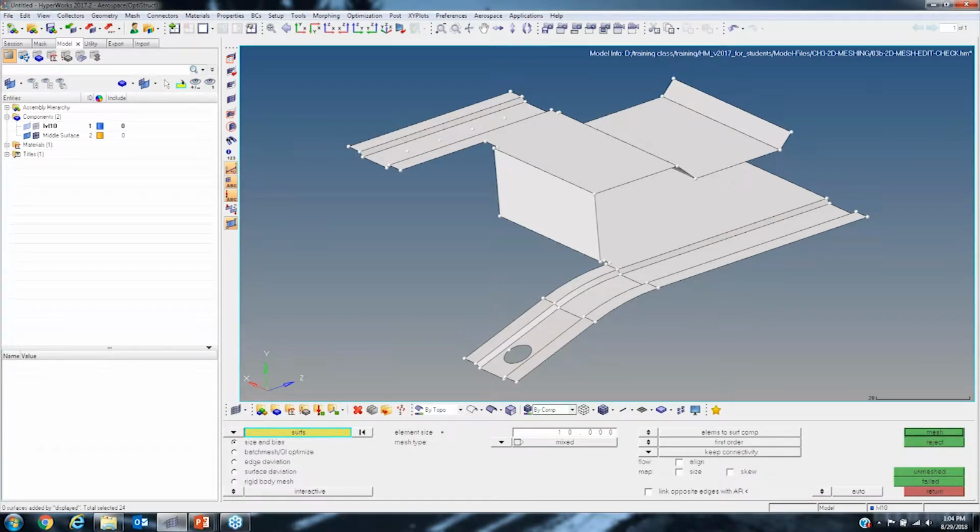So here we have this geometry, and I ideally want to do a quad mesh of the whole thing, right? So we're going to try to get rid of all of the triangular elements here. If I click on quads, we have this option between quads and quads only. The difference is that quads will still try to put in a triangular element here and there, wherever it finds it very necessary, but the quads only mesh will just set the whole thing to only quads, regardless of how much they warp off.